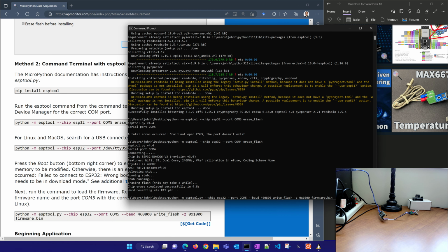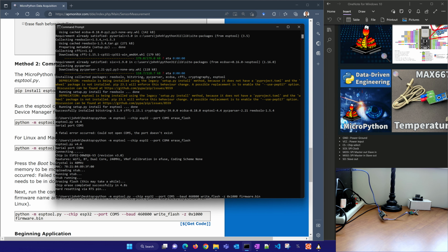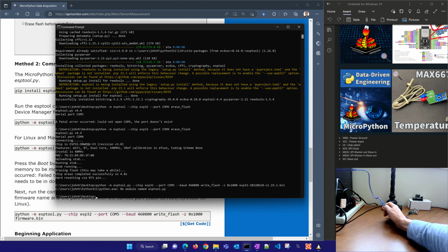Now this one is going to be just a little bit different because I have firmware.bin, but it's not firmware. If you just hit tab over, erase that, and then tab over, it'll eventually get to your firmware bin. Okay, so I'm going to go ahead and hit boot again because now I'm writing to it. So you always have to hit that little button in the upper left-hand corner when you're writing to it. Okay, so let's see, esptool.